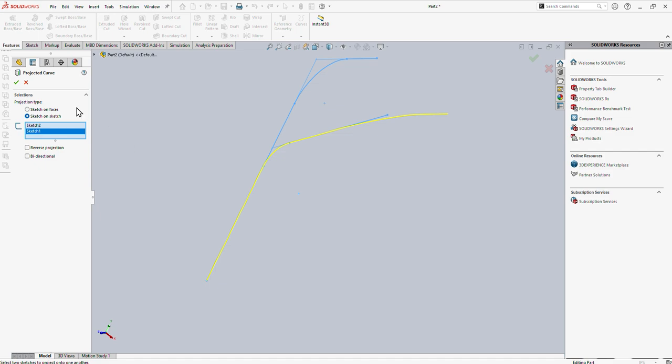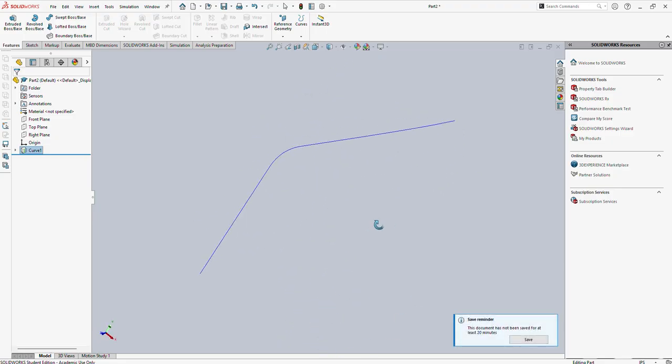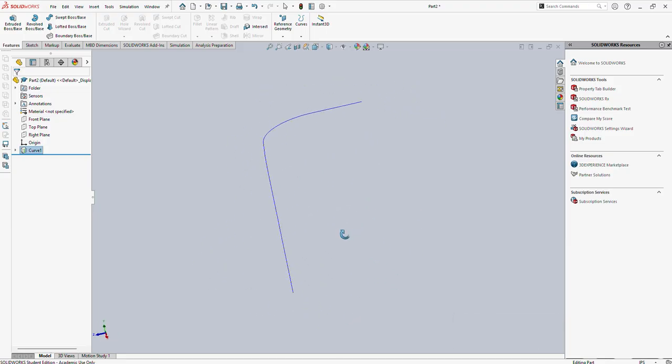Okay, and right click. So you see we have the curve. Using sketch 2 alone, we couldn't achieve this shape. This shape is important for us, and the way to do it is adding a shadow line and then giving this shape. That's how the curve function works.